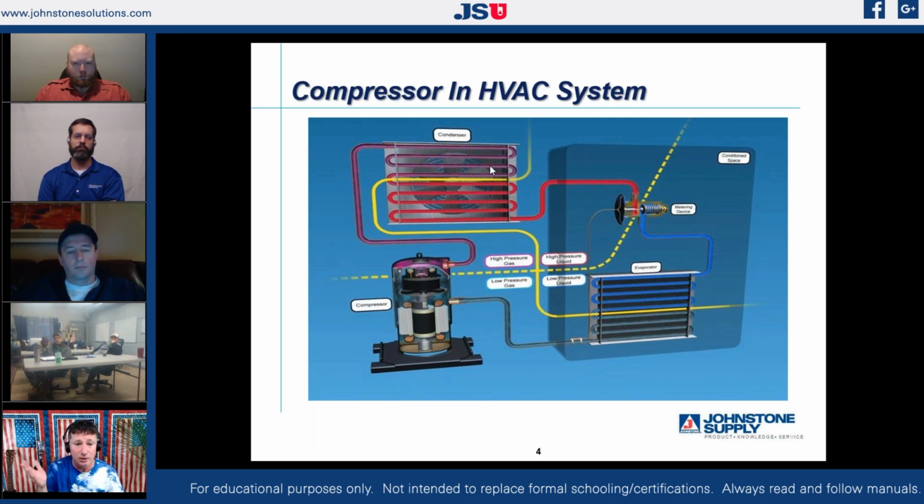So even in the winter, when we are running defrost in our vehicle, we are running hot antifreeze, hot water through our heater core to maintain the temperature in our cabin, but we are running our compression system so that we can remove moisture, because it's going to collect on our evaporator, just like a residential air conditioning system. We collect moisture on our evaporator to get it out of our system, right? If I have a moist cabin in my vehicle, how do I get rid of the moisture? I turn my air conditioning system on. And if I'm not comfortable, I turn my heat on to compensate for that. But we truly have the exact same compression system in every refrigeration system.